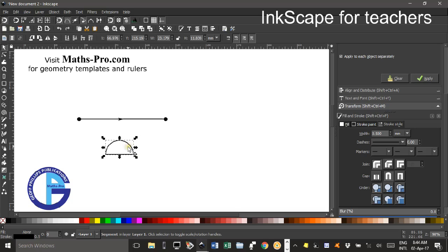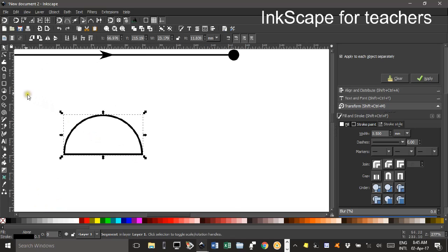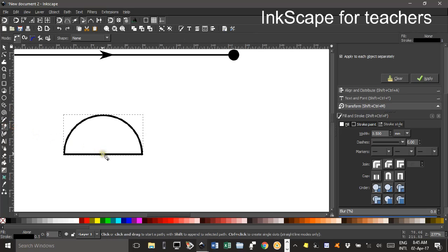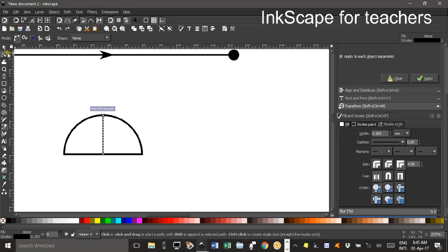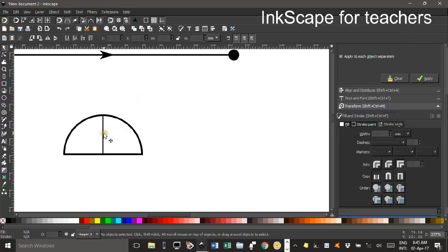I need a dividing line down the centre of those. I'll just zoom in and click the Bezier pen tool again. I'm looking for the midpoint of that segment, perhaps it's not selected. I think it's this one here, snap midpoints, yep, so if I click that, click, control to drag up, double click or click and enter, select tool, that line looks a bit thin so